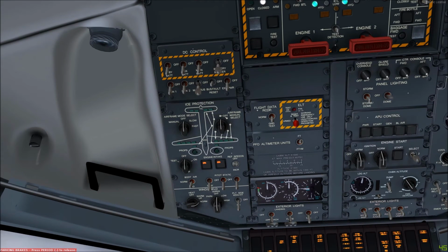The electrical system is monitored by the Electrical Power Control Unit, or EPCU, and following a fault, perhaps with one of the bus bars, then the bus fault reset can be momentarily depressed, and that will ensure subsequent monitoring of the system following a fault.